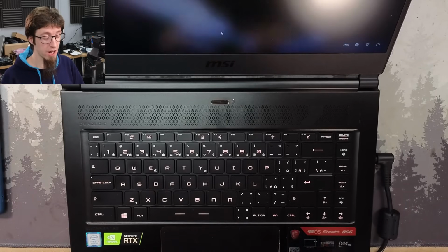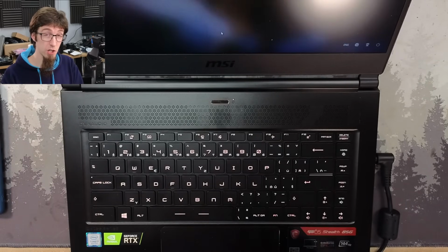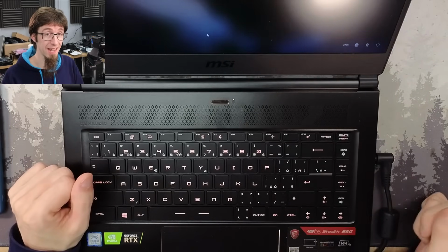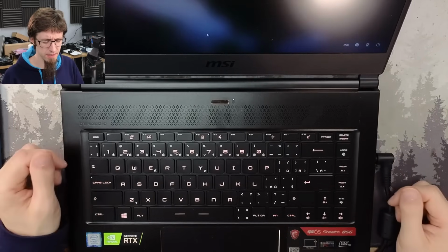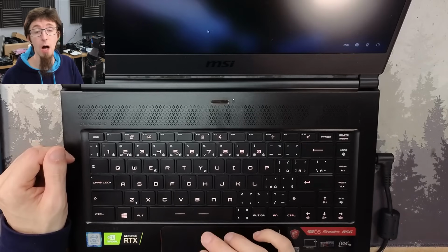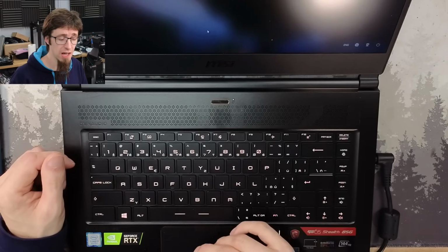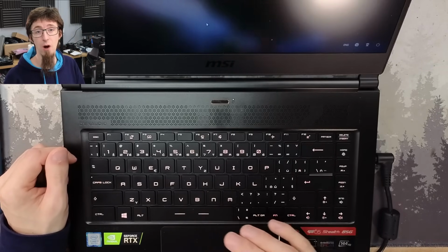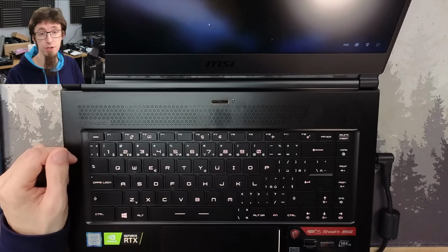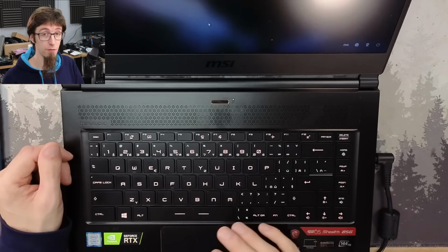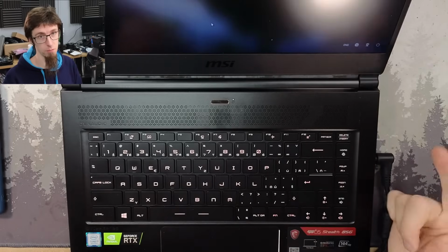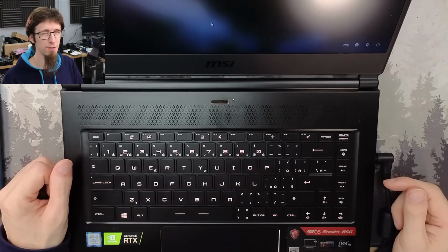So I did mention about checking if the inductor might be running a little bit hot because we put in a 2.2 amp inductor replacing the 3 amp inductor that was originally in there. However, this isn't really going to be a concern because remember, the screen is powered from the main power rail of the laptop, which means it could be running at up to 19.5 volts. So let's round that up to 20. And remember, we've put in a 2.2 amp fuse. So if we assume 2 amps, 20 volts times 2, that means 40 watts of power handling there, plus a bit extra because we're actually running at 19.5 and we've got 2.2 amps in there. So we've got like 40, 45 watts there.